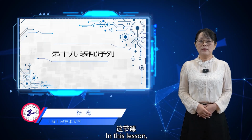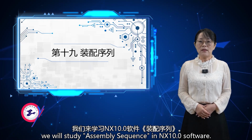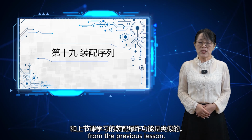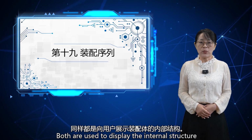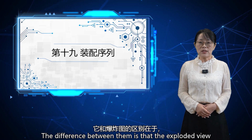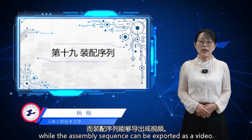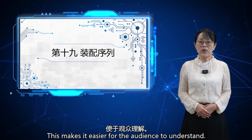Everyone, in this lesson, we will study assembly sequence in NX10 software. The assembly sequence we learn in this lesson is similar to the assembly explosion function from the previous lesson. Both are used to display the internal structure of an assembly to the user. The difference between them is that the exploded view is just a scattered diagram, while the assembly sequence can be exported as a video. This makes it easier for the audience to understand.